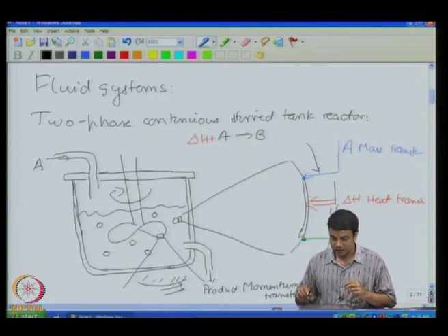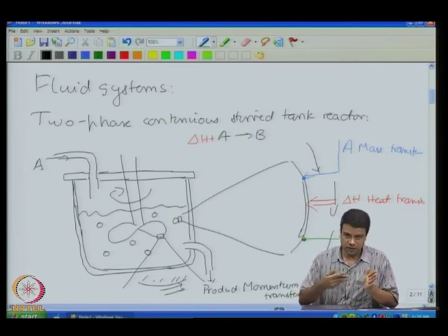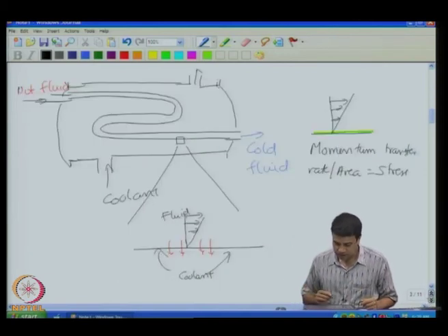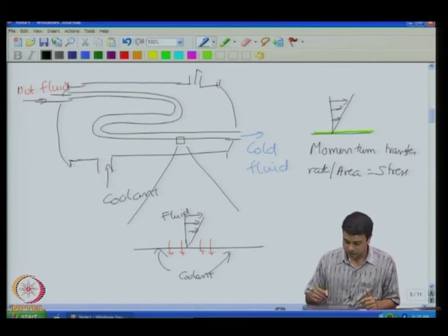Same thing with heat. The transport perpendicular to the surface, which is the only form of transfer that will result in transfer of heat, has to take place due to diffusion. At surfaces where there is no convective transfer perpendicular to the surface, because the fluid cannot penetrate it, transfer ultimately has to take place due to diffusion. Similarly, in the heat exchanger problem, convection can bring hot fluid into the tube, but for that heat to get across the surface, that has to take place due to diffusion. You cannot have convective transport perpendicular to the surface because there is no fluid going perpendicular to that surface.